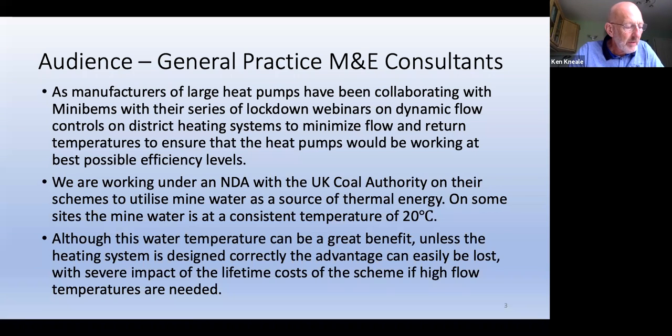There are specific references to mine water and the benefits of high temperature water, but the principles of the need for low flow and return temperatures will clearly apply to all heat pumps in all areas of deployment.